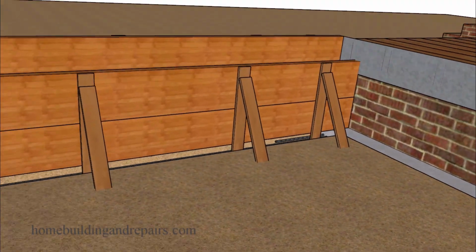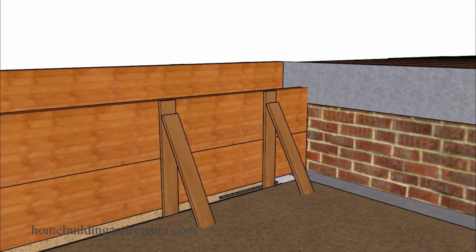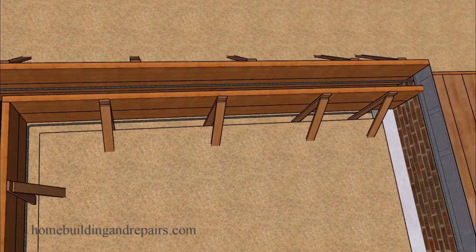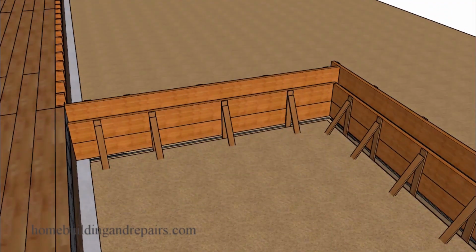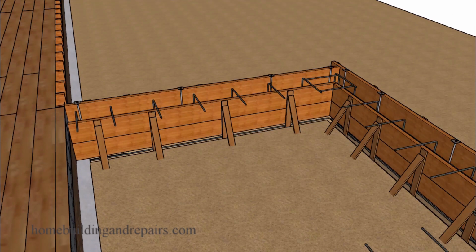And our form boards are going to be a little bit lower, or the thickness of the floor slab. And you can do this either way. I can either do it like this or raise the forms to the top of the floor so that the top of the stem wall will be the same height as the top of our floor. And I think either way will work fine. It will basically be up to you or your building designer as to what they choose to do. Just keep in mind that that is another option.